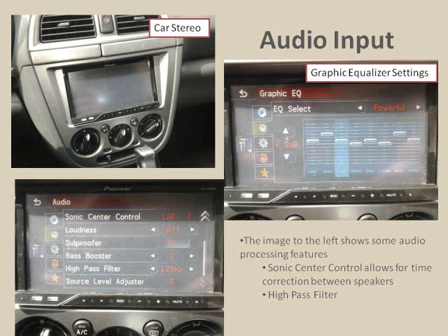In a car, the most important listener is the driver, and because they are not exactly in the center of the vehicle while driving, music is perceived to be emanating from the right side. To correct this and bring the music back to the driver's center, the music on the left channels will typically be delayed to ensure that both the left and right audio reaches the listener at the same time. This, in effect, creates a proper soundstage in which the lead vocalist appears audibly directly in front of the listener, with the other instruments to either side.